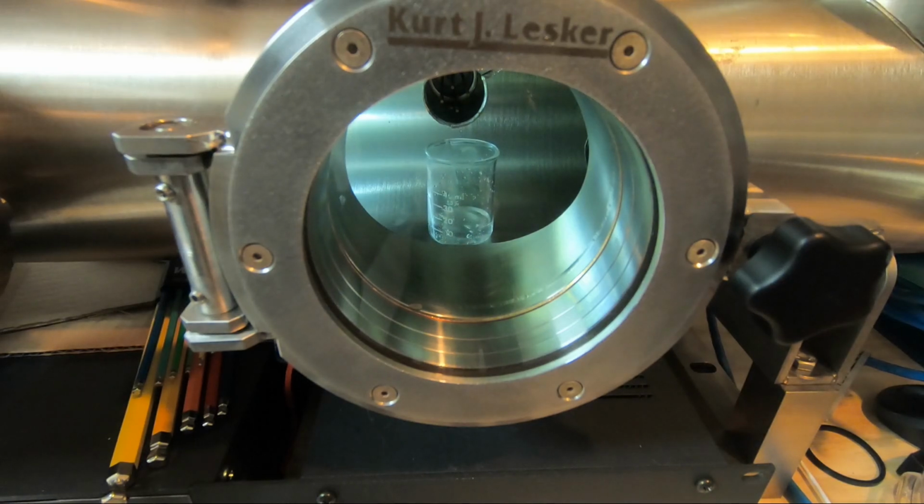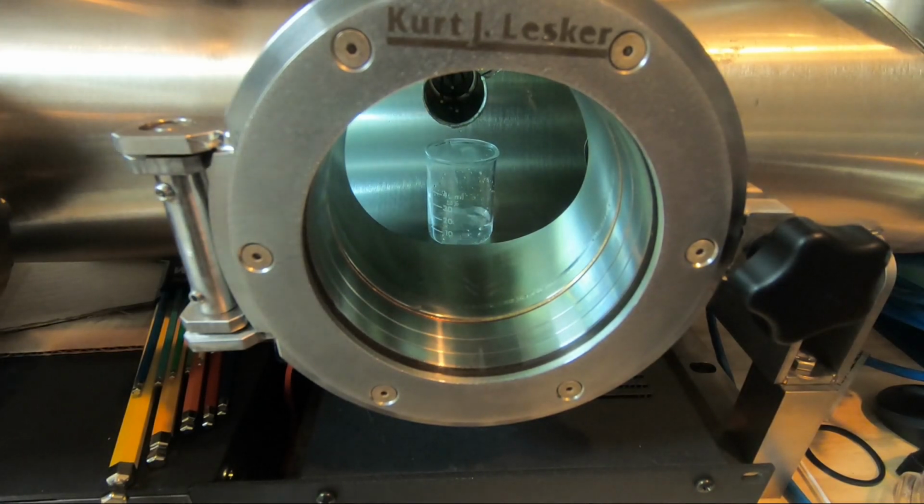Boiling again. I'm controlling the vacuum a little bit with the leak valve as well now, just to keep it from being too violent. It's kind of what we do with degassing epoxy at work as well. You pull the vacuum nice and slow at first, just so the bubbles don't get too crazy, and then you slowly start increasing the vacuum as you get more and more of the gas out of the epoxy.